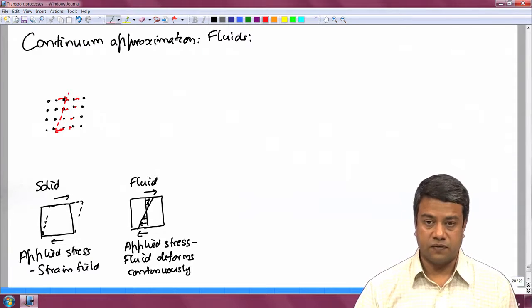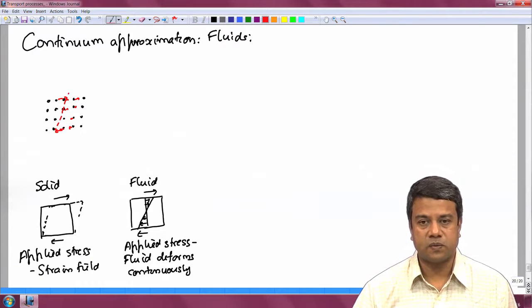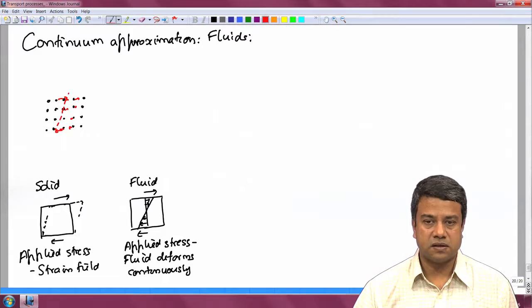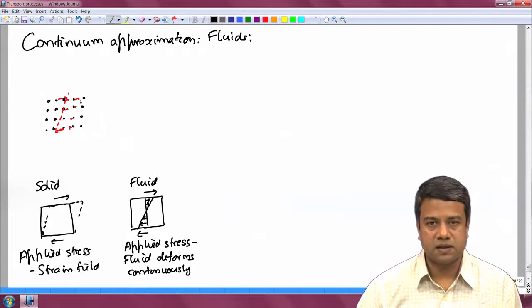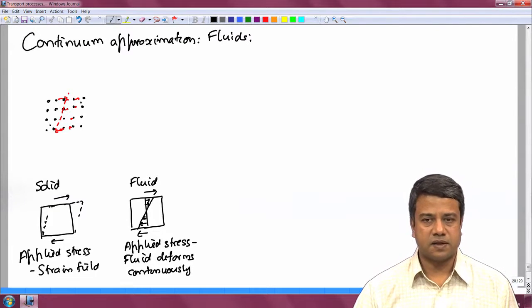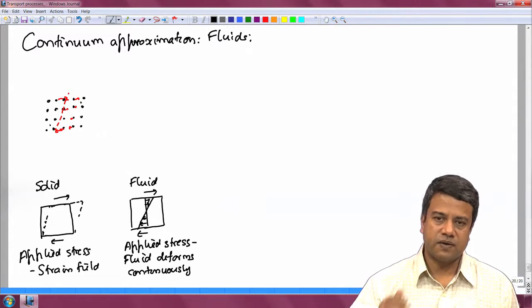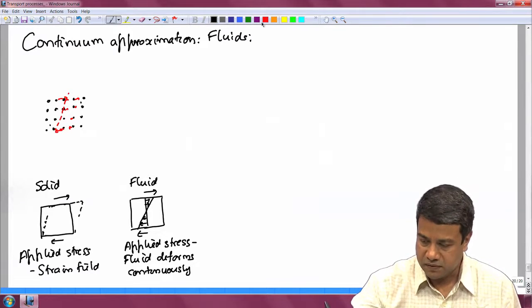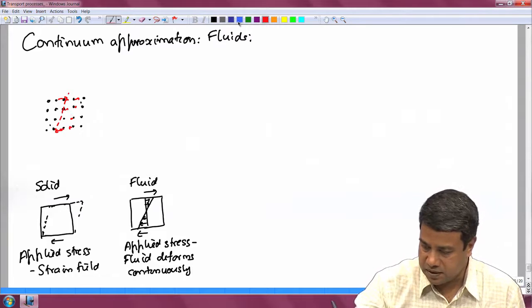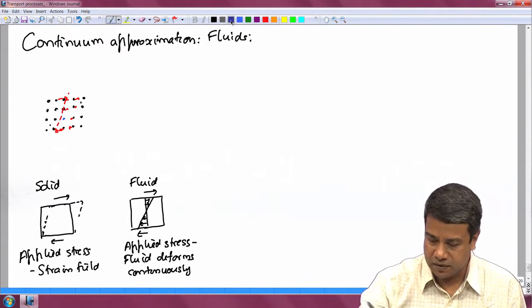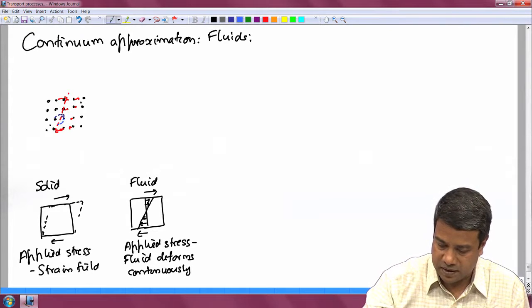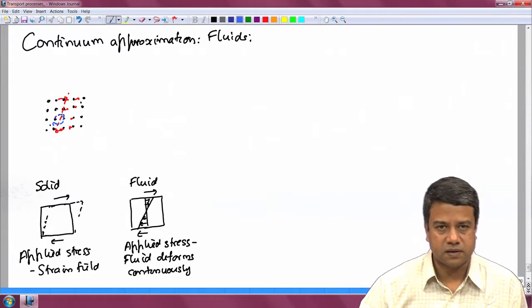There is of course diffusion in solids. It takes place by two means. One is the interstitial diffusion due to molecules which are imperfectly located within the interstitial space of the solids, and the other is due to vacancy migrations. Certain locations may not be filled with a molecule. So, if you have a vacancy within a solid at some location, you could have another molecule move in, and consequently the vacancy actually migrates the other way in a solid.